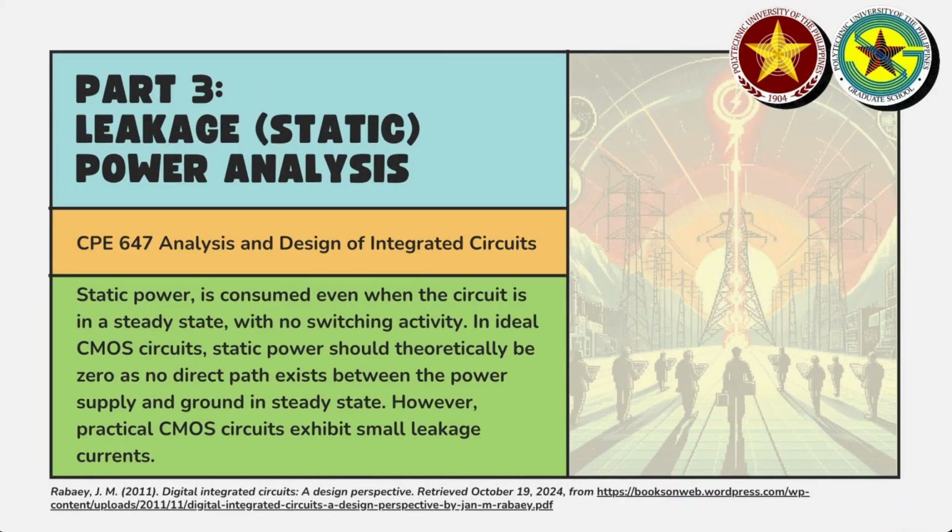Part 3. Leakage static power analysis. Static power is consumed when the circuit is in a steady state with no switching activity. In ideal CMOS circuits, static power should theoretically be zero, as no direct path exists between the power supply and the ground in a steady state. However, practical CMOS circuits exhibit small leakage currents.